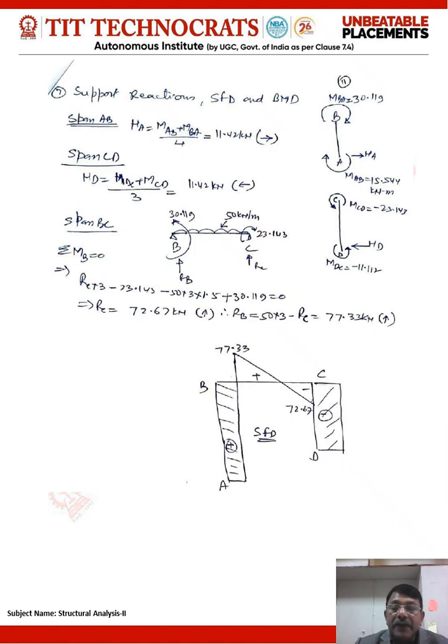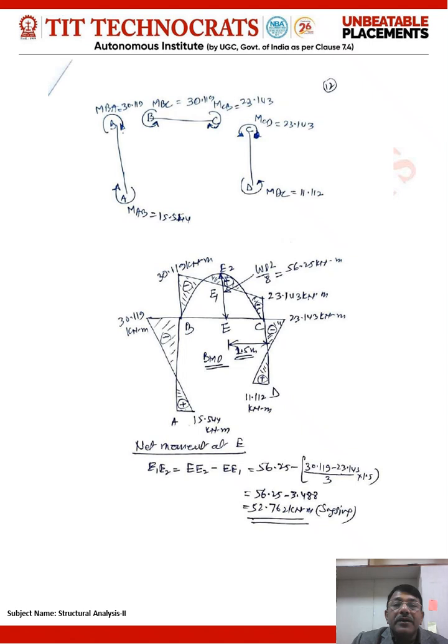Then, after finally getting all the values at the base of the column and all the beams and columns, they can be analyzed for their reaction forces and the moments, and the required shear force diagram can be drawn as shown here in the illustration, and the required bending moment diagram for the frame can also be prepared as per your previous knowledge.